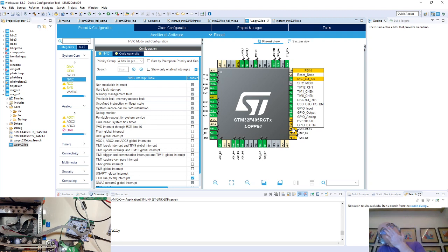And actually, good tip, if you're bringing up an STM chip, the newer ones use a peripheral called an SAI, which is a serial audio interface. And they typically have 2 or 3 of them. And each one has an A half and a B half, and therefore you get 6, basically. And it's super flexible, and it can do TDM and I2S and all these different formats. And you can configure them half duplex, full duplex, blah, blah, blah. And it's all very modern and very lovely.